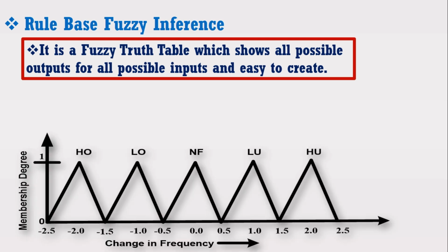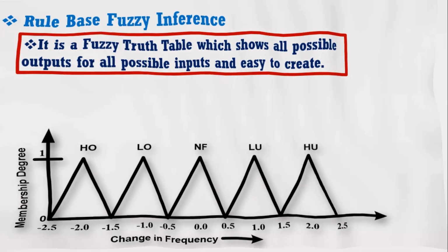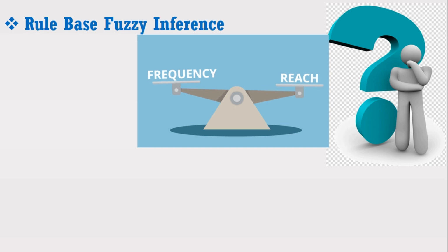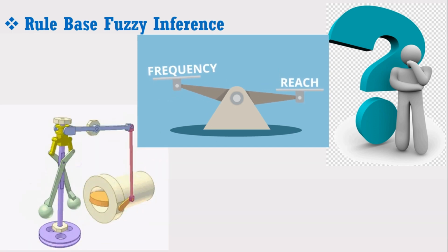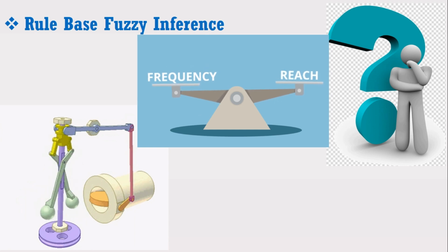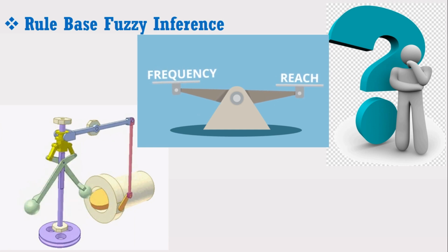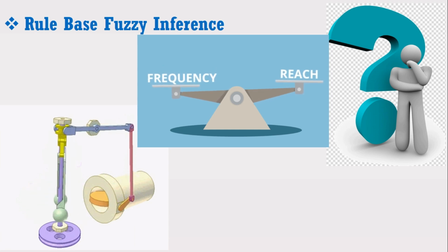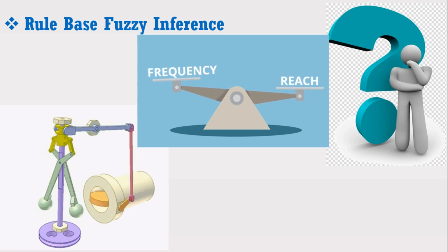Let's consider the same example of load frequency control. We have to assign the rules to the fuzzy logic controller. Just think carefully. When load is increased, frequency is decreased. Now what we have to do? Can you imagine? What should be our signal? Whether to open the turbine valve or close the turbine valve? The correct answer is we have to send the signal to open the turbine valve in order to increase the generation. Therefore, now the rule will become as below.